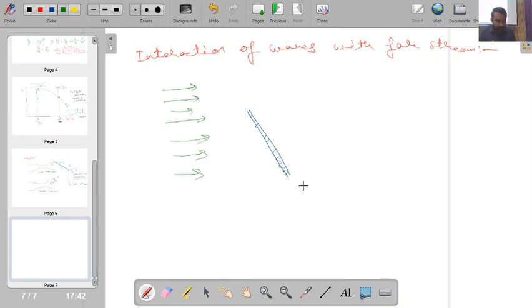Say this shock wave has originated somewhere over here at this point from the bottom portion. Up to this point, as the shock wave is expanding, just above this everywhere I will have flow at pressure P infinity. Behind the shock wave also I will have pressure P infinity. But any streamline which is passing through this will bend, something like this, and say this is point 1 and this is point 2.